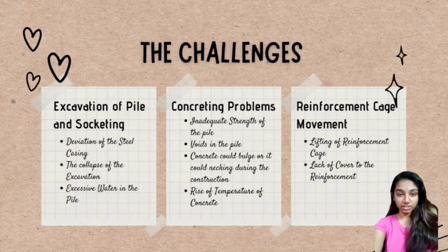There are many issues that we need to look into when the pile excavation or drilling is done. Let us start with the challenges. There are three main types of challenges of pile foundation: the excavation of pile and socketing, concreting problems for concrete piles, and reinforcement cage movements.